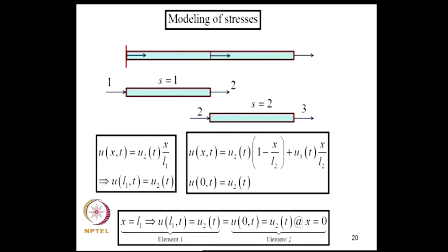Now, let us talk about another aspect of modeling which we have not touched upon till now. We have now been able to formulate the problem in terms of nodal displacements, and within an element we know how to interpolate the displacement field using the values at the nodes and the interpolation functions. In our analysis, we are not only interested in displacements, we are also interested in strains and stresses. So, that issue is what I would like to now discuss.